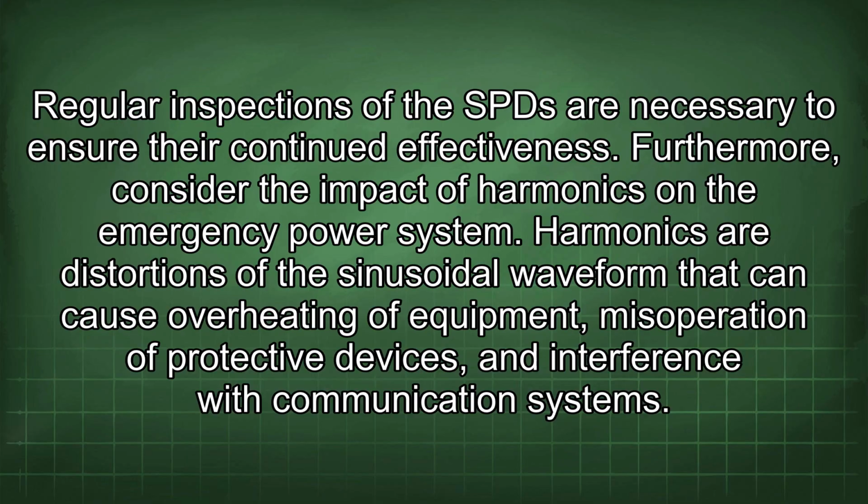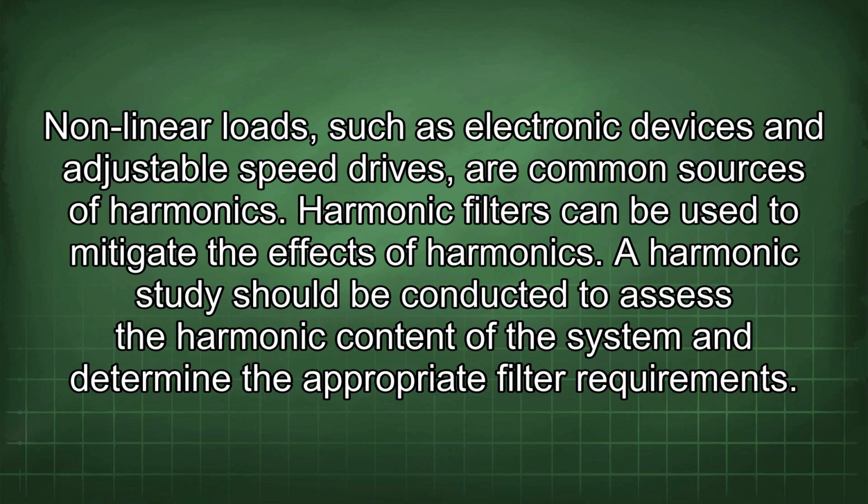Furthermore, consider the impact of harmonics on the emergency power system. Harmonics are distortions of the sinusoidal waveform that can cause overheating of equipment, misoperation of protective devices, and interference with communication systems. Nonlinear loads, such as electronic devices and adjustable speed drives, are common sources of harmonics. Harmonic filters can be used to mitigate the effects of harmonics. A harmonic study should be conducted to assess the harmonic content of the system and determine the appropriate filter requirement.